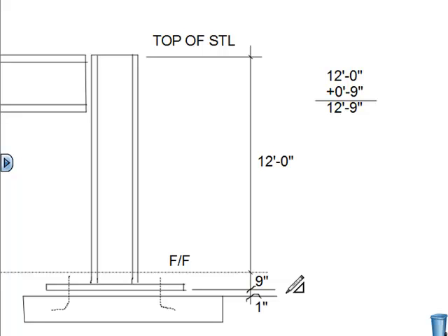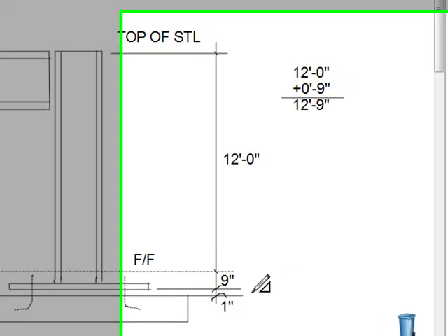And on page 118, they do show you the little formulas. Floor line to the top of steel, plus the floor line to the bottom of the base plate, equals the total height of the column. So you don't include that built up grout or mortar between the foundation and the base plate. Does that make sense to you?